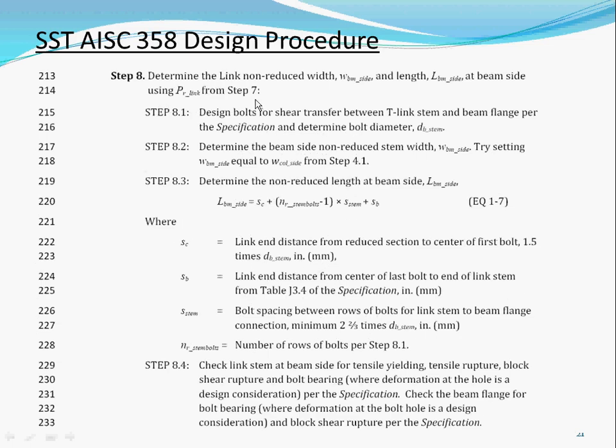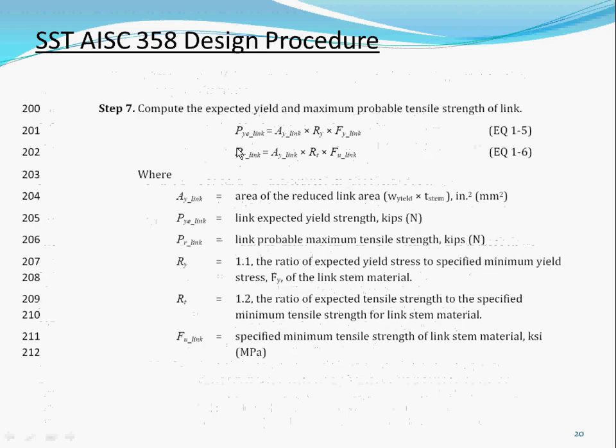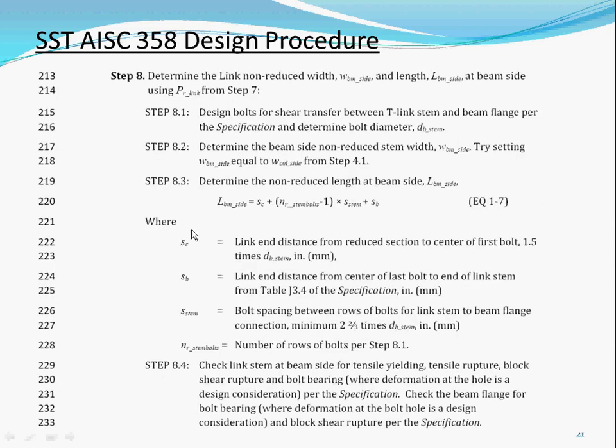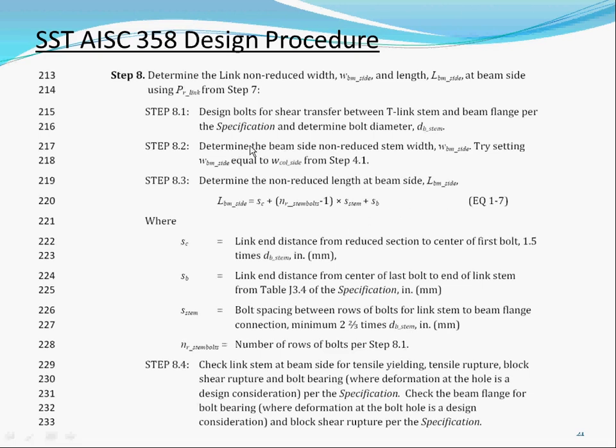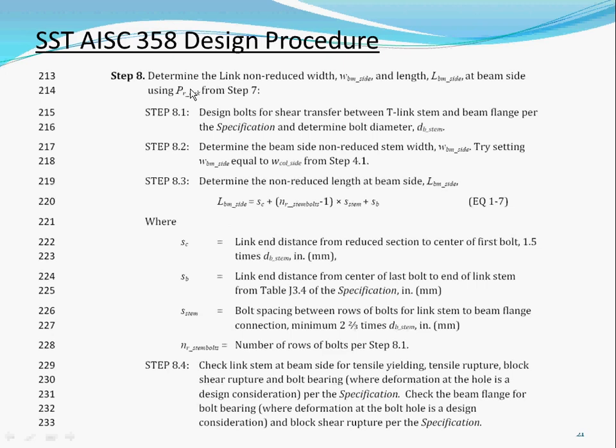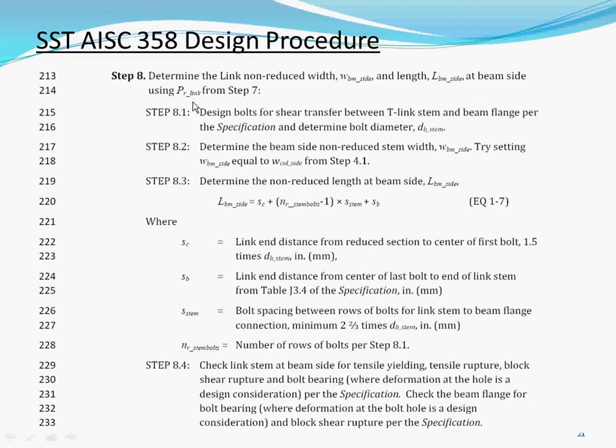Now after you determine that, then you size the other side of the bolts and all that stuff for that term to design it for the PR link. So we're designing everything for this higher load. So all the bolts that we're sizing, make sure we could size the bolts to be greater than that. So this is what we're calling the fuse capacity, I guess. And you're designing everything else to be greater than that fuse. So that's what we're doing.